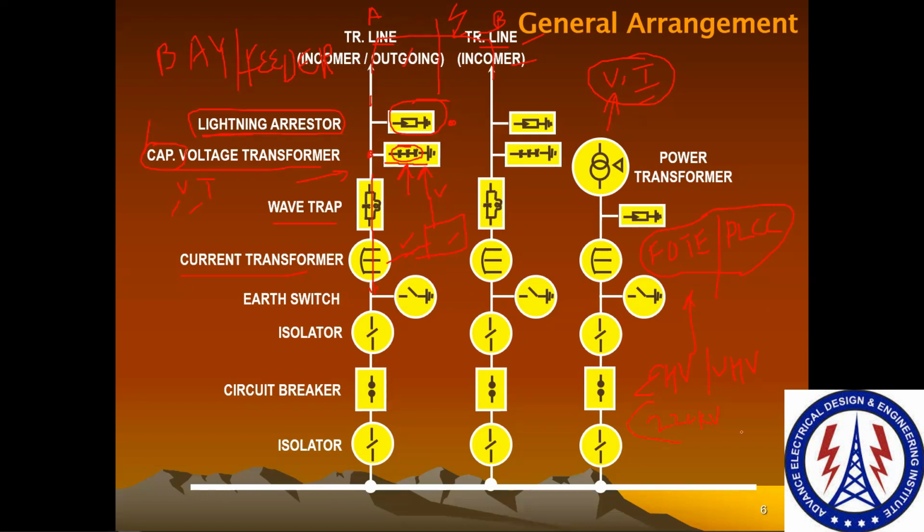Whenever your substation is above the 220 kV level, you will provide this capacitor voltage transformer, because in that case we require the PLCC communication channel.